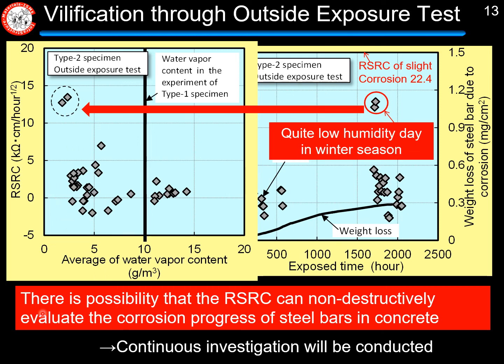So we conclude that there is a possibility that the RSRC can non-destructively evaluate the corrosion progress of steel bars in concrete. However, we should also consider the humidity effect, so continuous investigation will be conducted.